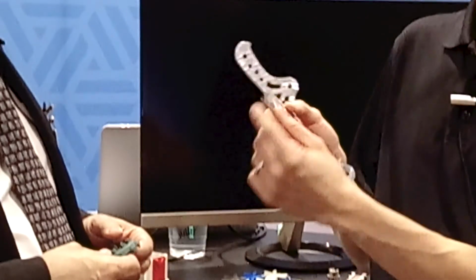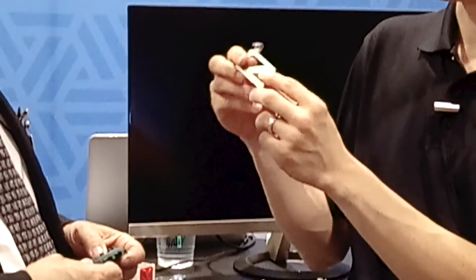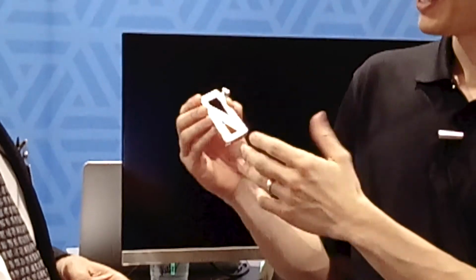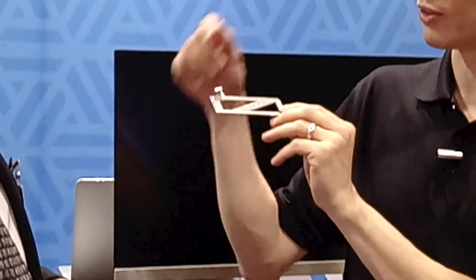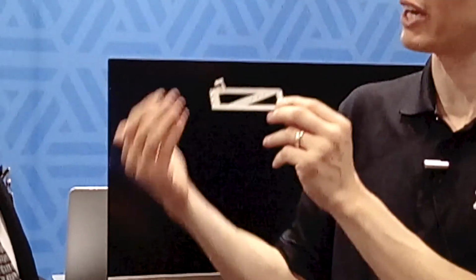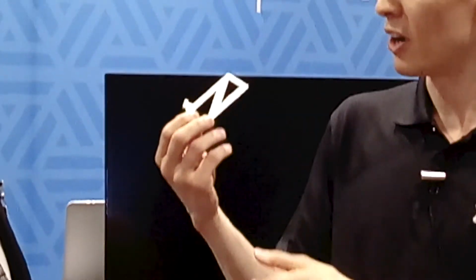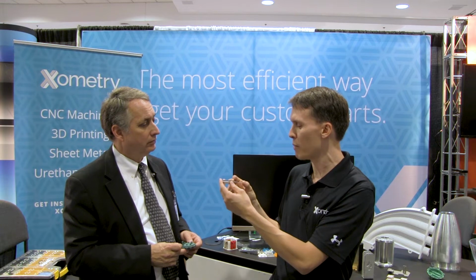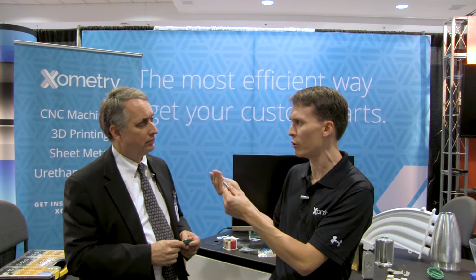I'm going to steal it from you for a second, because with this piece here, a lot of people may think, hey, I need this quickly, so let me 3D print this out of metal. And they'll go and they'll upload it to our site, and they'll click 3D printing, they'll click metal, and they'll see, okay, here's the price in stainless steel, here's the price in alumina, etc. And they can actually see that right there. But honestly, this part is designed for sheet metal fabrication. So I would actually recommend to that customer, check out what the price is and the lead time in sheet metal. It actually may be one extra business day to get exactly what you're looking for.